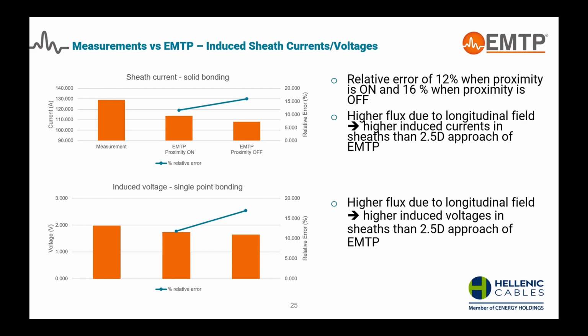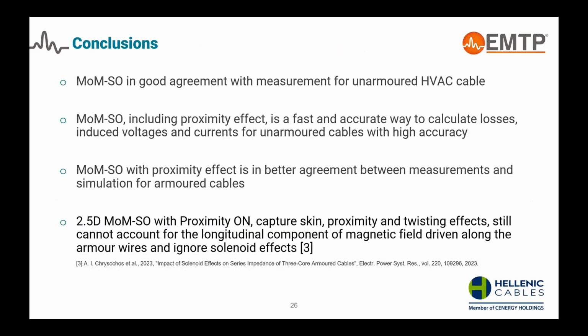For the single point bonding, again, the higher flux due to the longitudinal field leads to higher induced voltages in measurements than the 2.5D approach of EMTP. And this is briefly described in the paper that I noticed here and presented recently in the IPST conference.